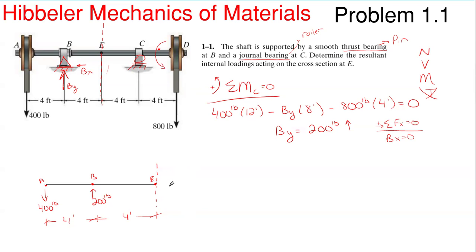So what we're going to do is apply these 3 internal forces just like reactions, and we're going to solve for them just like we do reactions. So we're just going to apply them in a direction. I'm going to apply N going this way. I'm going to apply V going this way, which is my shear, and then my moment like this. So why did I draw them in these directions? Well, this notation right here is considered positive directions for these internal forces.